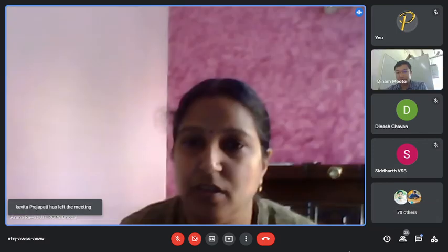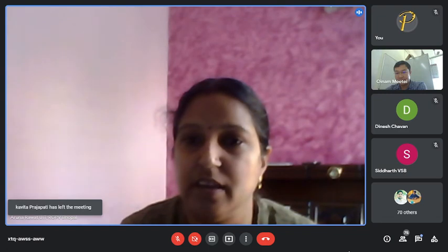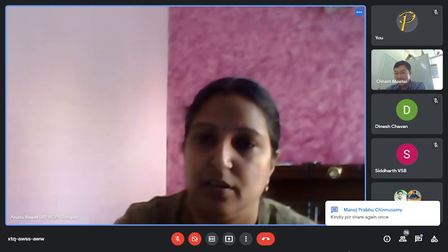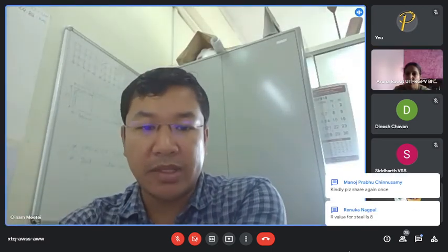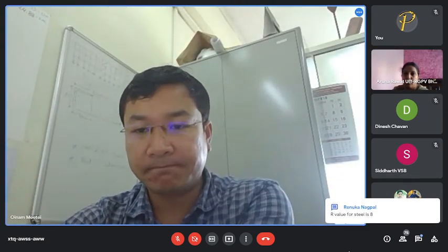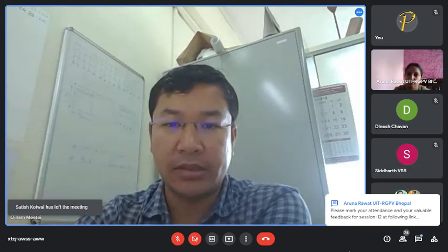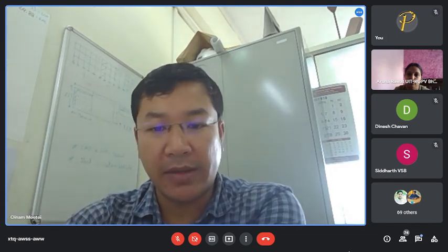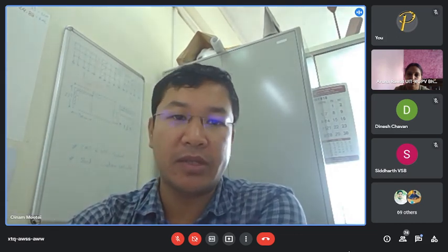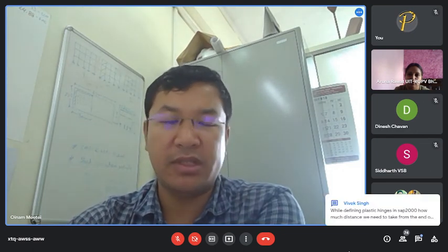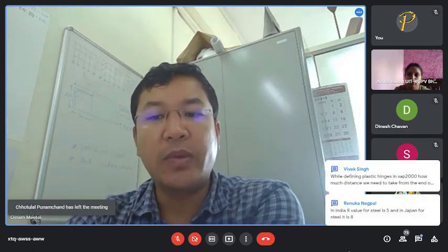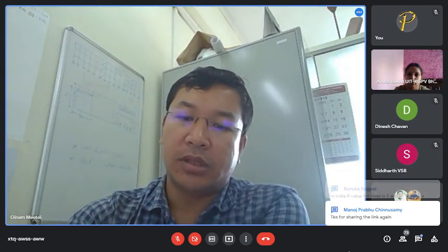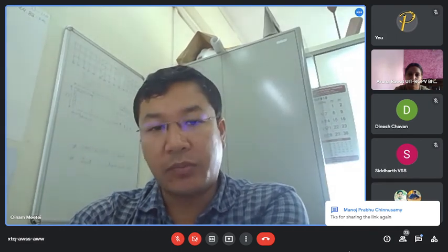There is one question. Can performance-based design help in reducing the steel reinforcement requirement of the structure? Yeah. So performance-based design means allowing nonlinear deformation. In elastic analysis or elastic design, of course, you have very heavily reinforced sections. But in performance-based design, we optimize. This is a kind of optimization approach. We are reducing some of your cross section as well as your reinforcement.